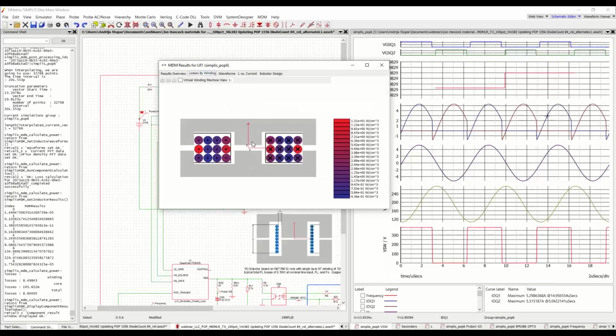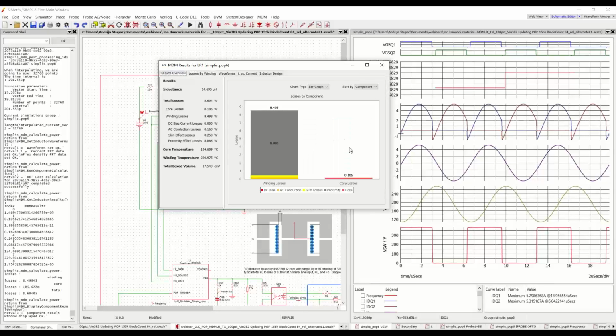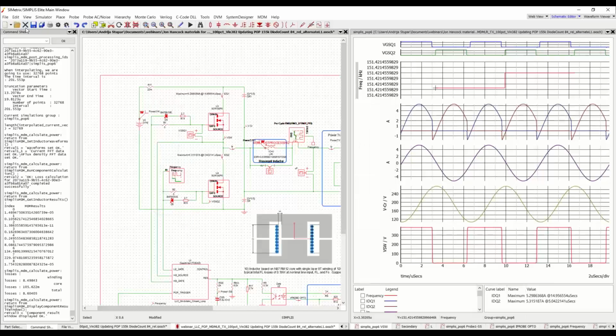And you can see why, because we have this big air gap, and we have 3 of them, and those proximity fields are just doing the damage there. And even though we pick a big wire, we fill the thing with copper, we have a low RDC, but the proximity loss is just criminal. So, you know, we have to chuck that one out the window.